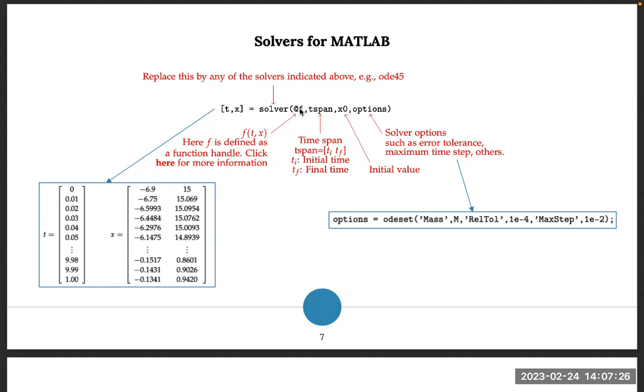So we're calling the MATLAB function f that we have defined in our code or any other file. tspan is going to be the time interval from t0 to tf. So we have to specify our simulation, our approximation is going to be from 0 to 30 seconds, for example. We have to say that as an input to the solver.